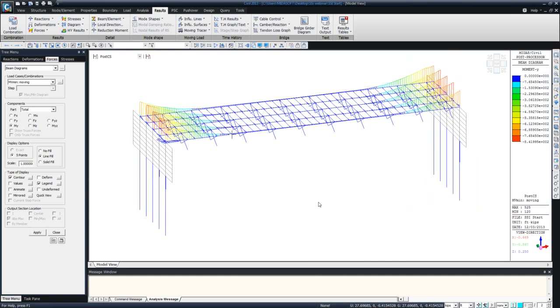As I said earlier, when we install the cross frames and the steel girders, it shows you a simply supported bending moment profile. Then you apply the wet concrete load on top of it. The concrete hardens eventually, and then it becomes a rigid connection at the abutment and the deck. When you perform the moving load analysis after the bridge has been fully constructed, you will obtain the negative or hogging bending moment at these locations. So this is how you obtain the results.